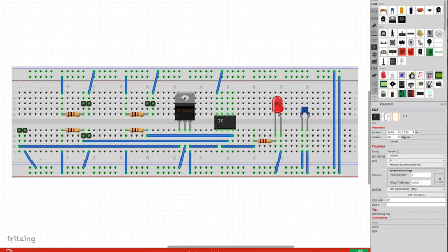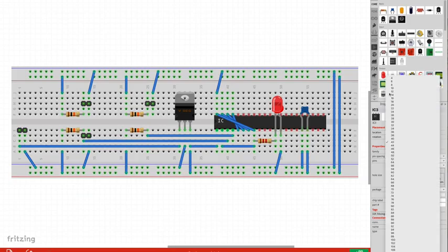Okay, so here's the MERG lighthouse circuit laid out on a breadboard in a very similar way to what we've just seen in the previous example. I really want to talk about the IC. This is a generic IC as contained in the parts list. Now, you can change a lot of things. You can change pin spacing, but 300mil is the standard pin spacing for a dual inline chip. You can change the number of pins, but it gives you some strange results for a part that's already partly connected. But it can be done, and that's fine.